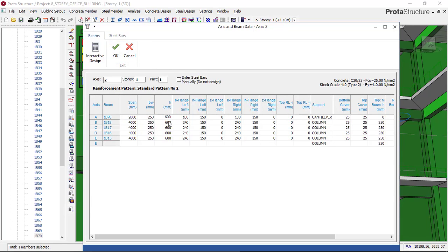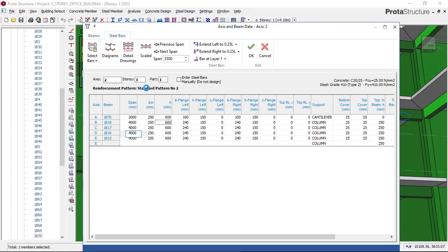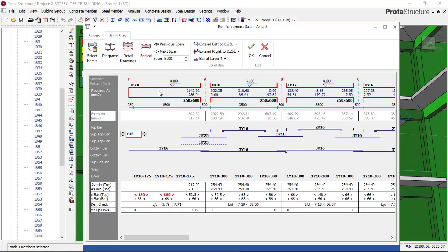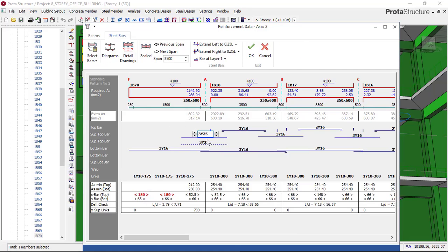So do this right now and then click on what's here, and then click on this place and then okay, and then go here and check, and change your reinforcement. So we can now go right here and click here, and this is update first, and then try to change your size of reinforcement, this to be 20 if that's okay. And then I can make this 20 and increase this to 4, because it's not really that good to use 25 because of the cost efficiency. Okay, so right now you can see that this is now okay.